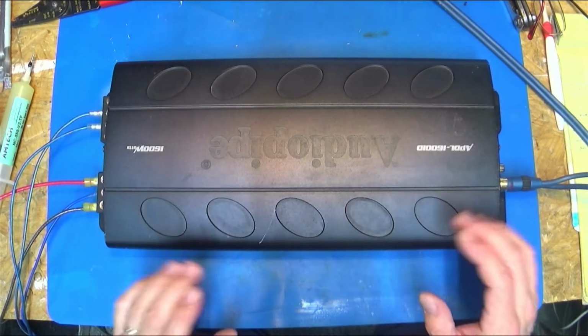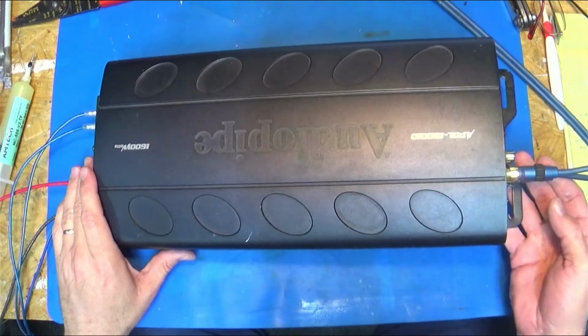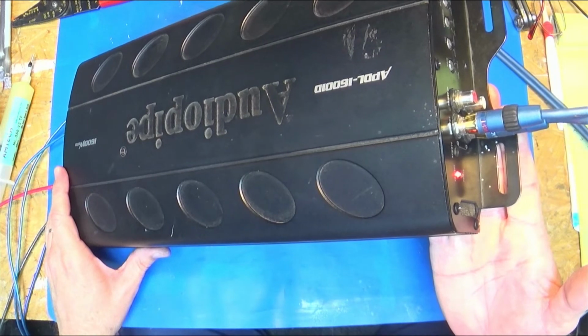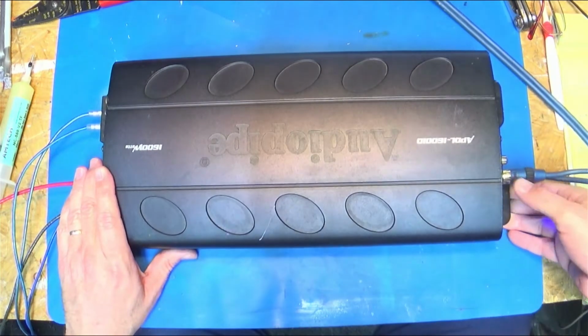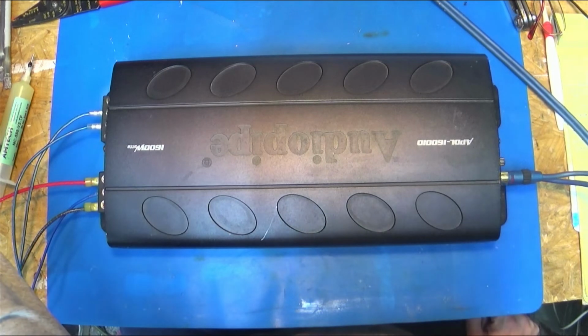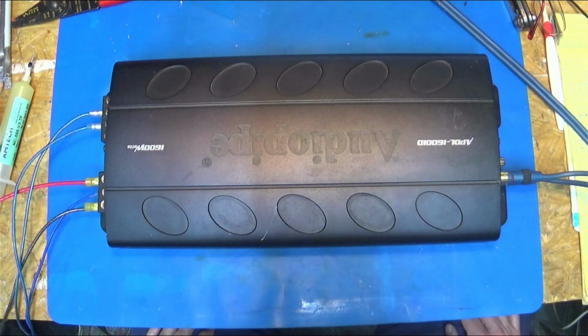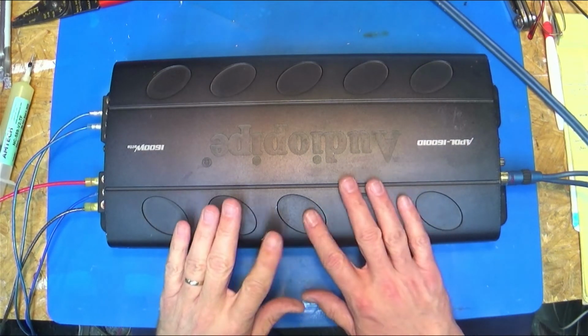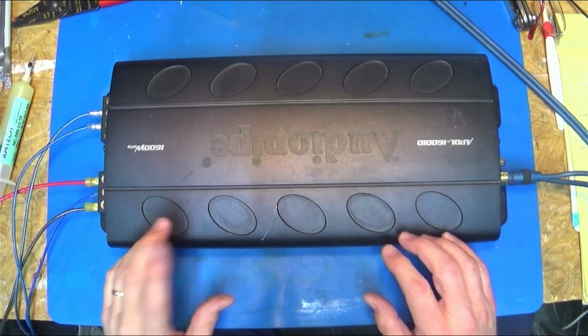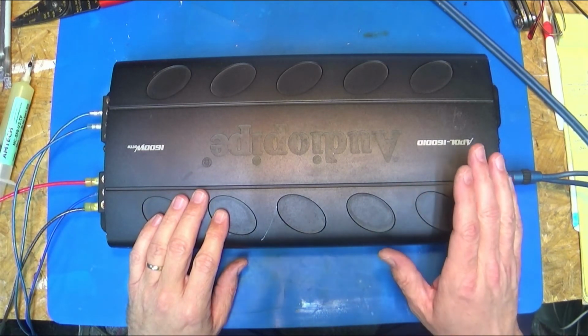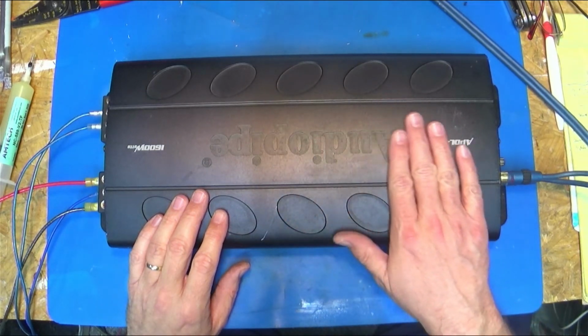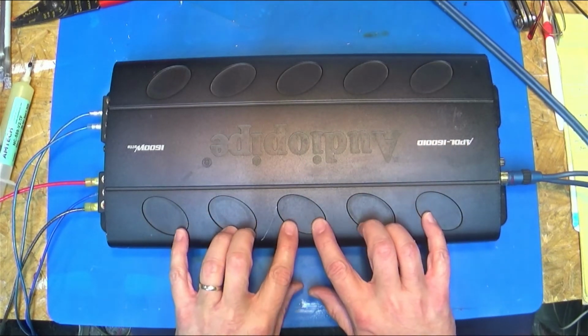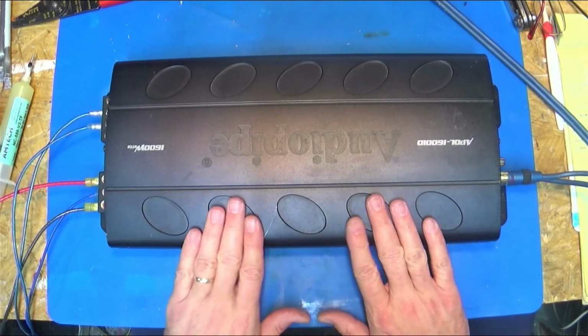Well, you guys didn't think I would let you off there without listening to it. So we go power on. Here it comes up. Turn the volume up here. Still got to cook it in, but it's all done. It does draw a lot of current on startup, more than my little supply will like. It likes the bigger supply much better. It has some lower value discharge resistors on the rails, so it does take a bit of inrush there to get them things charged, and that's it.